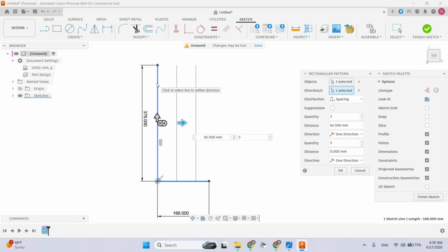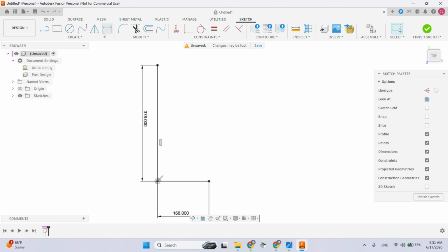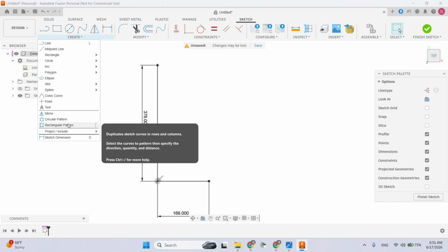And we're going to need a total of 3 lines, but 4 total if you count the starting one. And the distance between each line is going to be 42 millimeters. Did I do that right? 1, 2, 3. I guess, is it 5? Yeah, 5 lines to create 1, 2, 3, 4 grid squares. Yeah, that's correct. Okay, and then it's called rectangular because we could also drag out a pattern in this direction, but I don't want to do that. Oops, so now I just hit Control Z. So get that back.